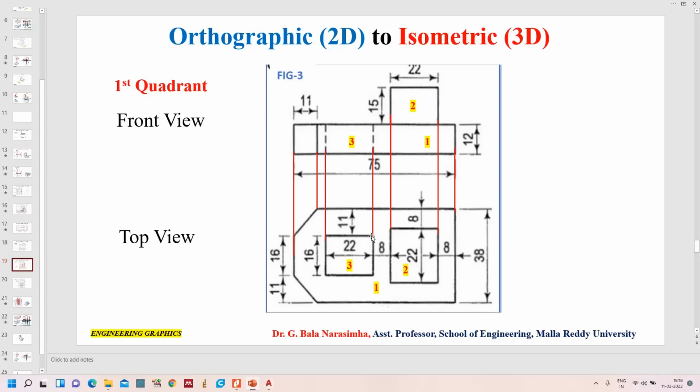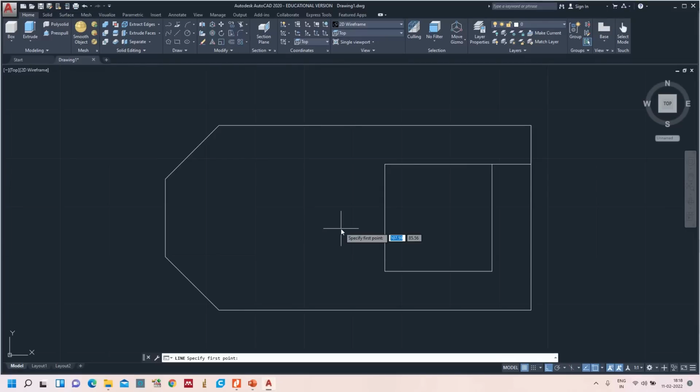Now we need this coordinate. So what is the place? If you consider from the top, it is 11 and from here 8. So we can draw a line from here 8 mm, but this distance is 11. Here is 8. Simply you can see here the gap between the square block and rectangular block is 8. Okay, perfect. And now already we have given 8 mm from here, but this distance is 11. So simply I am going to take 3 mm extra.